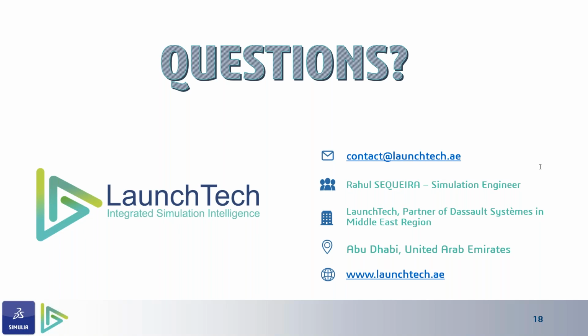However, if you're thinking about, let's just say, metal forming or casting applications, then you would obviously require loading situations like either the Johnson-Cook plasticity or other cyclic loading equations. For example, if you're thinking about a piston cylinder, then maybe a cyclic loading plasticity model might be required for that. In the end, with calibration, all you do is combine your plasticity model and the hardening model to represent a real-world simulation of what might happen experimentally.